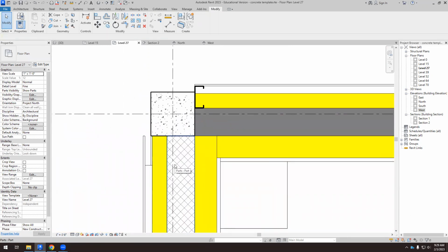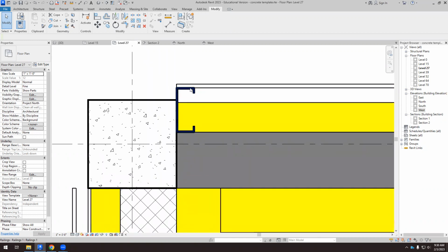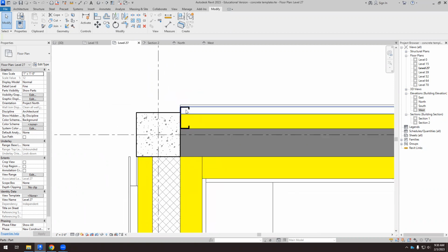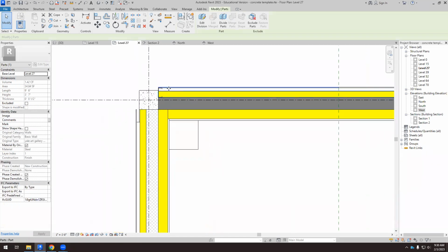Okay, so again, this is some advanced feature because here we can see different things. The structure element is the most important one, so that's why it has a thicker line. And then this is something important, so I can make it hatched in black like this. So this is a solid element, but it's not structural. It's a structural element to hold this, but it doesn't bear the weight of the building. It just bears the weight of this external finish here. Okay, I think it's interesting.